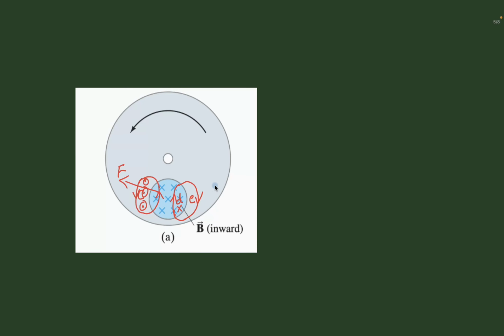So by allowing high currents, or electromagnets to be generated or produced there, while the disk is running, due to that electromagnetism the disk will develop some eddy currents, and those eddy currents will experience some opposing force which will instantaneously bring that disk to rest. So these can be used in the transport section, where the braking systems of bikes or cars can use them.